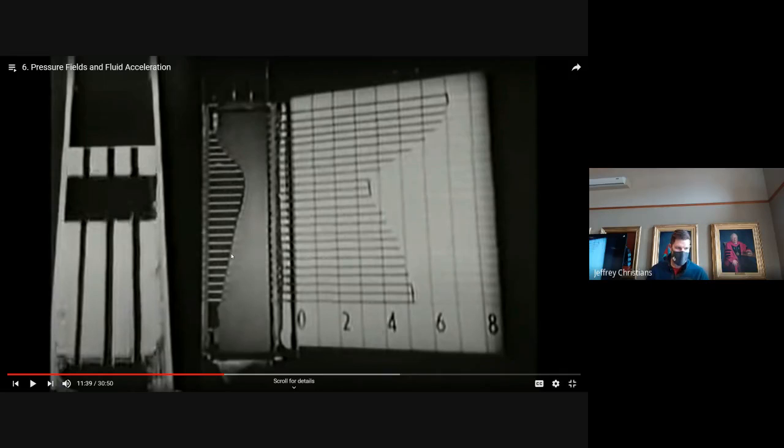You can see some of this effect if you look at table 8.3 at the bottom, like what's happening to the K value at different angles. Basically, with a very gradual expansion we have very few losses. But if we have a very rapid expansion, we get boundary layer separation, which basically means the object has a big wake behind it, which gives us more frictional losses.